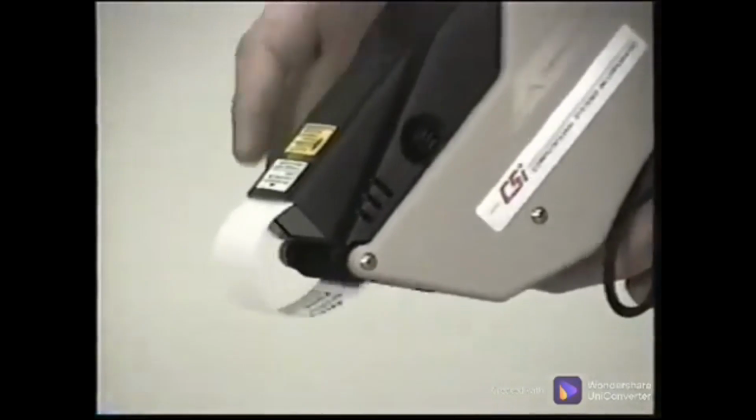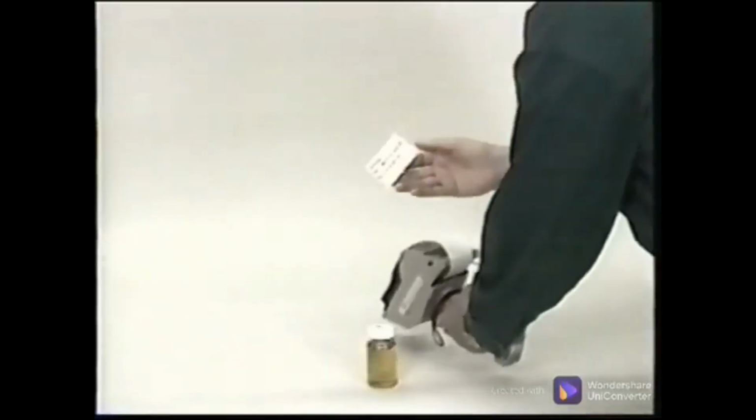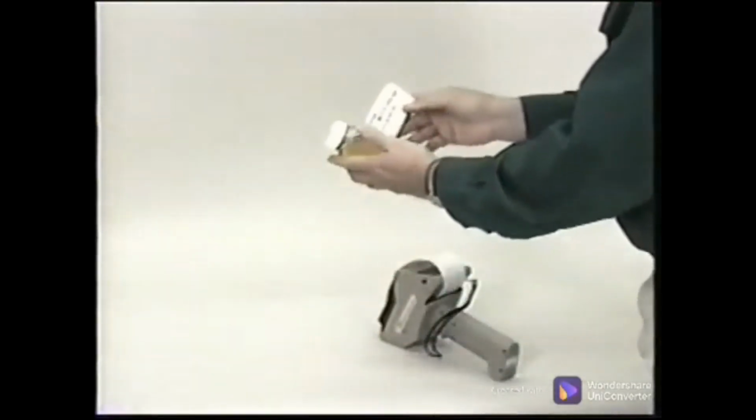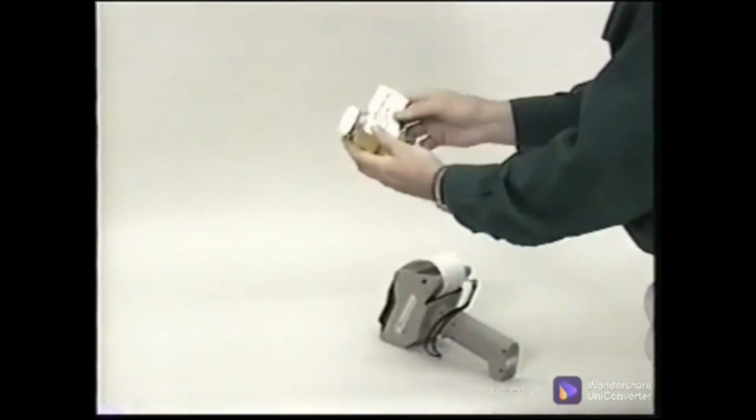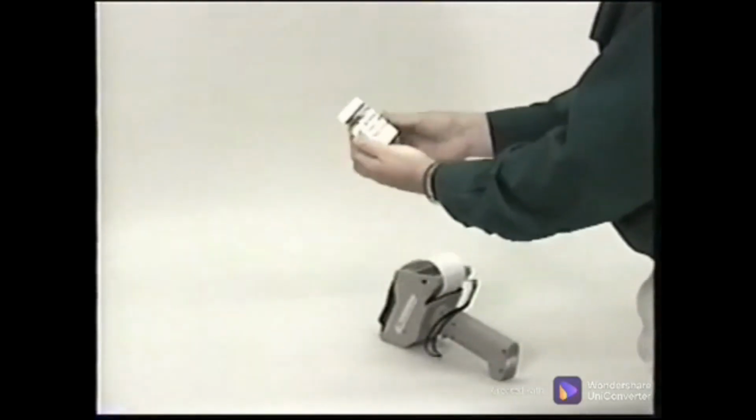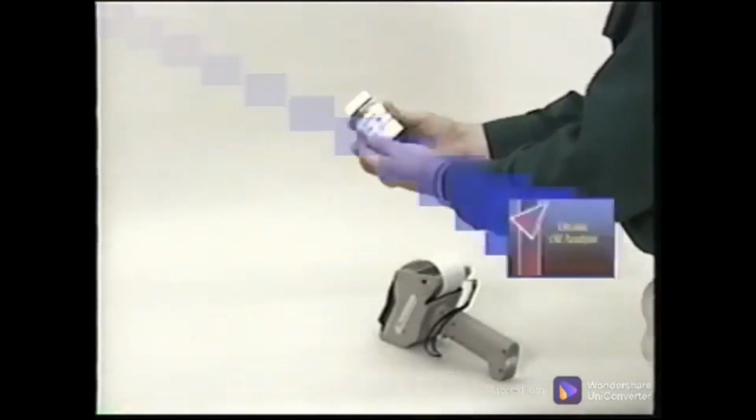Label each sample bottle with the oil type, the machine from which the sample was taken, and the sampling date. If a sample is diluted prior to testing, the label should reflect that fact. A sample taken from an unknown source has no value. Mislabeling of your sample might lead to unnecessary and costly maintenance actions.